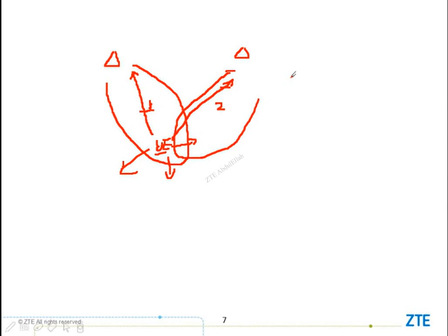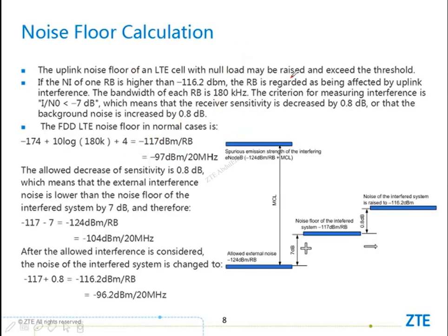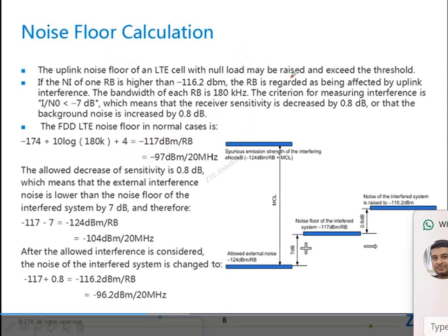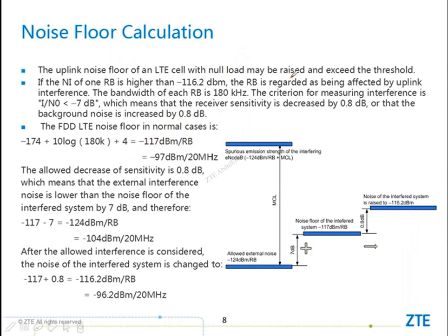Similar to the downlink, usually when we control the downlink coverage, the problem of overlapped and overshoot coverage, it is also helpful for the uplink. Okay. And for the uplink interference, even if there is no interference, because there is some noise, still there is a basic value.